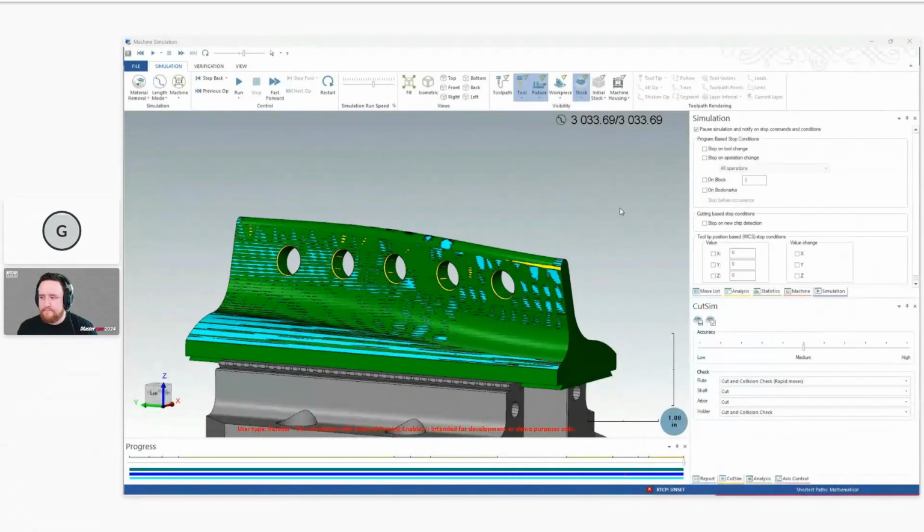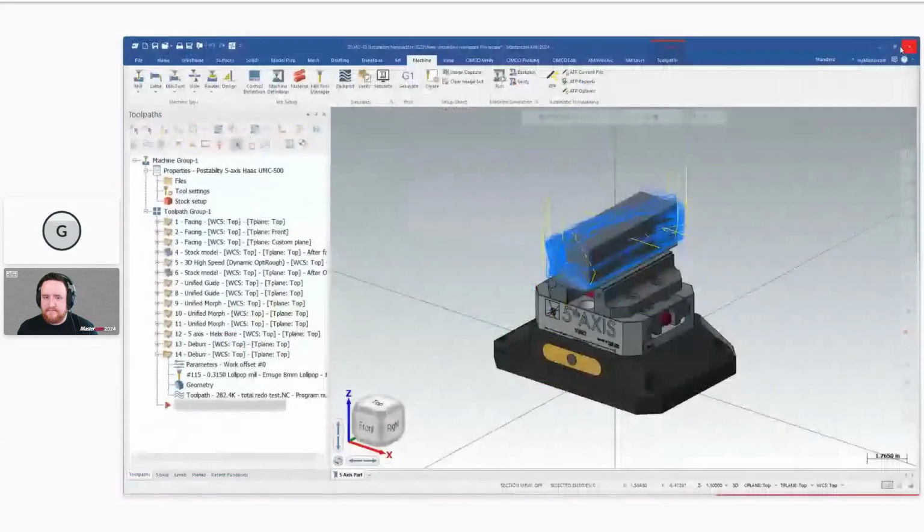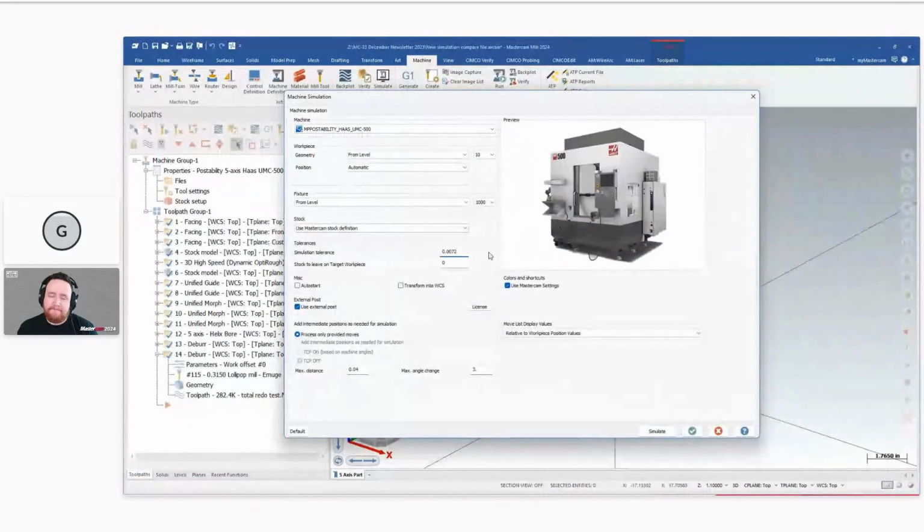By having a larger tolerance, it allows you to compute faster. And in the compare feature, you might see that faceting or those gouges that might not otherwise be there, but that has to do with that tessellation tolerance, allowing the simulation to get away from the toolpath motion more than it needs to. That could, of course, be tightened up. It's a lot more work on the CPU, but you'll get more accurate comparisons if you're lowering that to like 1/1000ths of deviation. Right. Yep.